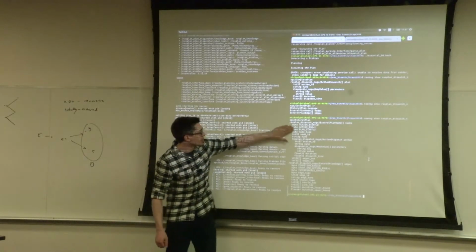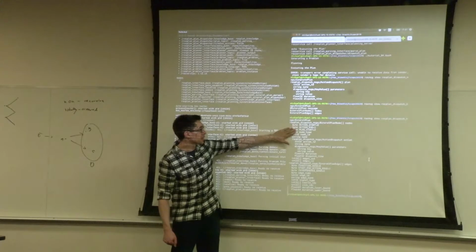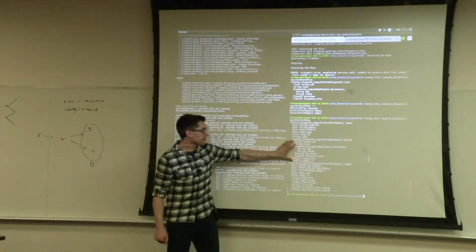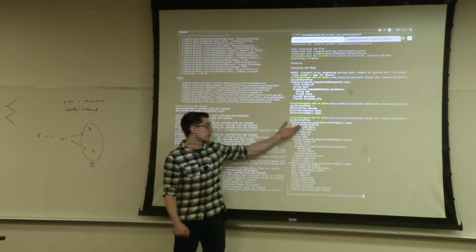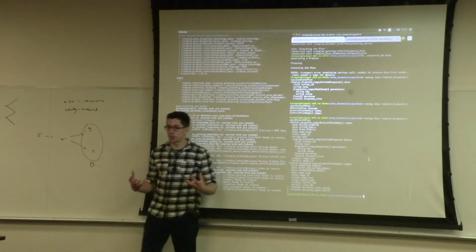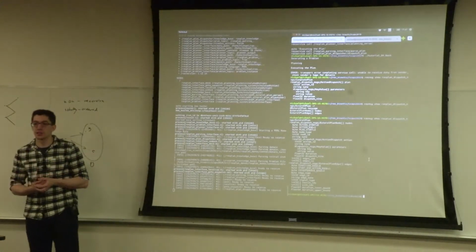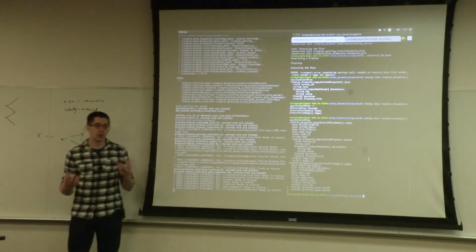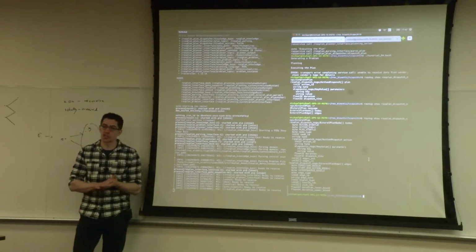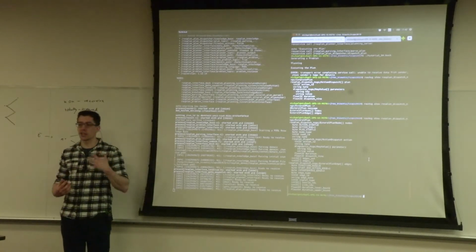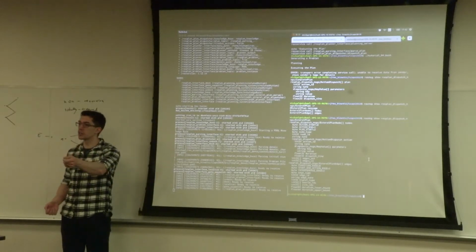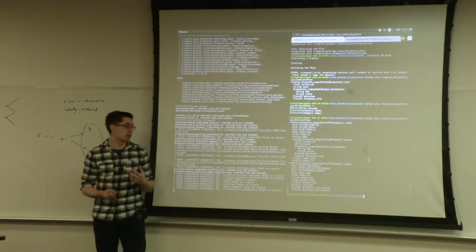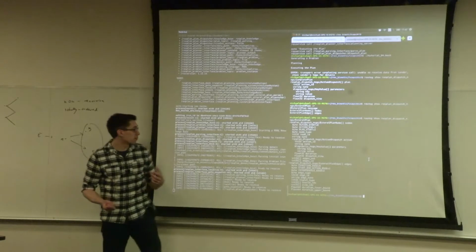each node can represent an action start, an action end, or the plan start, and has a node name, but also within it, it has an action dispatch. So every node represents, apart from the plan start, the start or the end of an action. Even the instantaneous actions in PDDL are represented as a start node and an end node, because in ROS anyway, there's no such thing as an instantaneous action, because every action takes at least the amount of time to publish the action start and to subscribe to the action response. And that's going to be a few milliseconds, but it can be important.